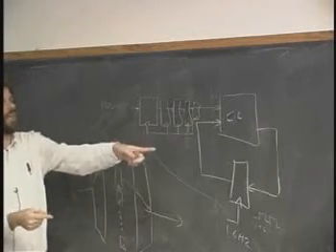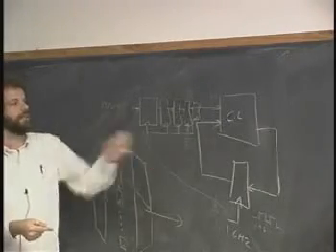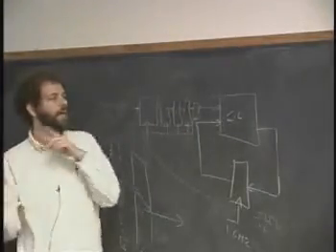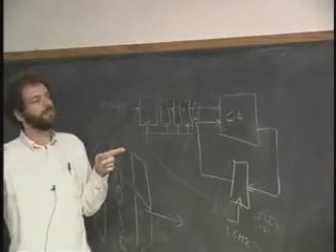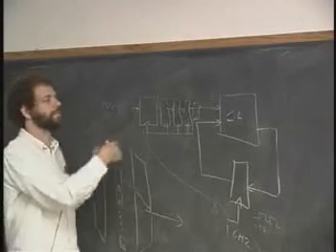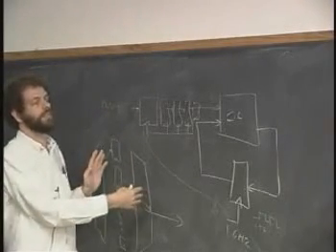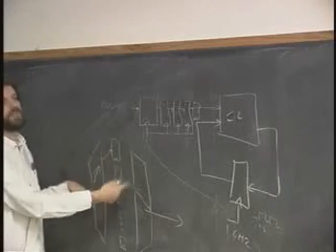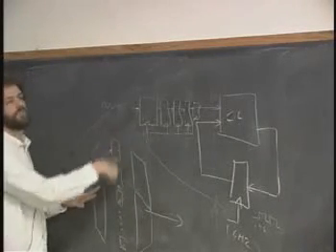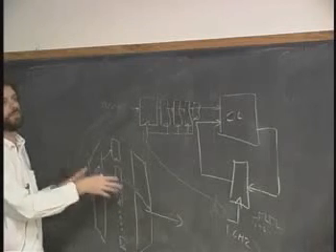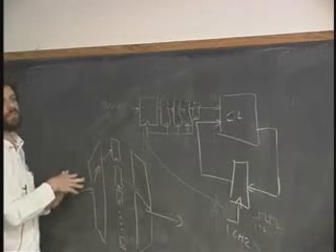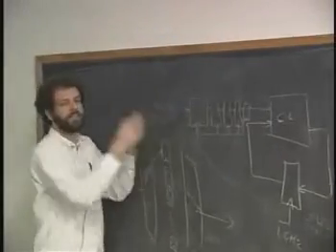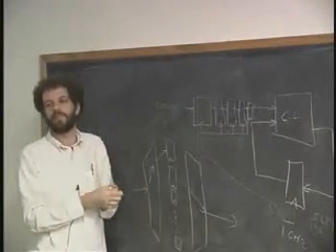So I could give you a job, saying, start figuring this out. Then the next billionth of a second, I give you the job, and I give you the job, and then by the time I get around to you, I've gone through 100 students, and you've had 100 billionths of a second to get the job done. And so this is an alternative way of spreading out the job amongst 100 flip-flops. Okay, and both of these are in fact used when dealing with asynchronous inputs from the outside world, as well as the other methods of slowing down this clock here or gating it and just kind of being blind to it for a certain length of time.